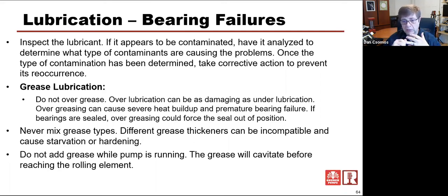That's going to be the next longer life to a grease for life bearing under normal circumstances. But again, it's dependent upon somebody going out there and greasing those bearings every so often. Motors have to be greased. Vertical pumps have to be greased. There's no choice. Horizontal pumps, you could do an oil bath, you could do an oil mist, or you could do a grease or grease for life. We have all four choices available for horizontal pumps.